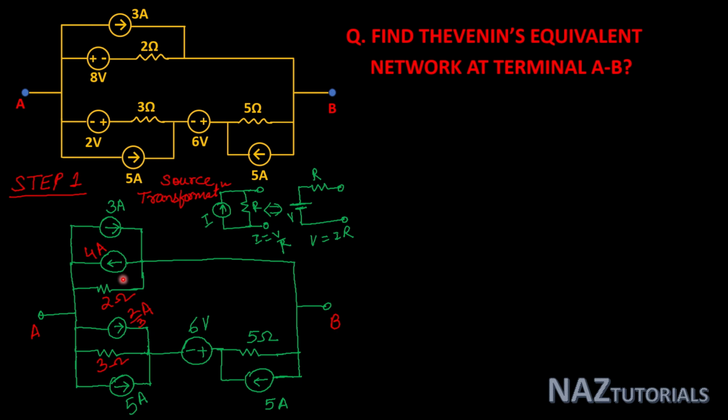current sources algebraically. So here both the directions are opposite, so the net resultant source will be 4 minus 3, that is 1 ampere in the 4 ampere direction, and these two sources are in the same direction, so it will be 2 by 3 plus 5, one current source in the same direction.